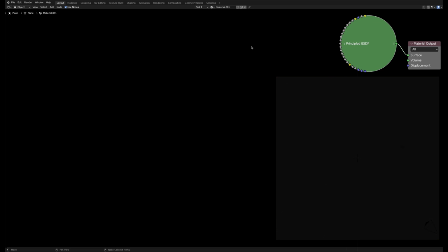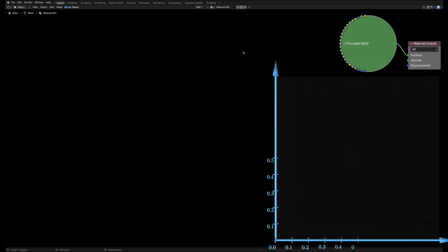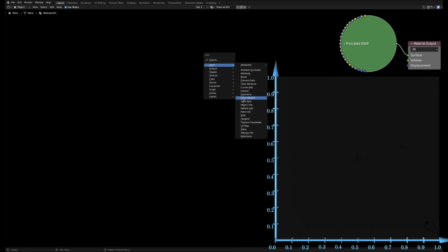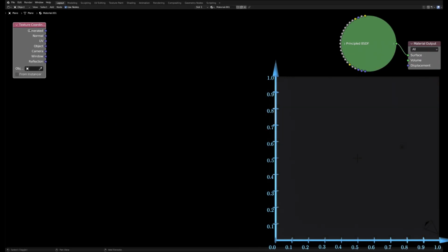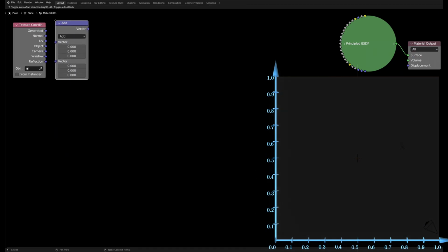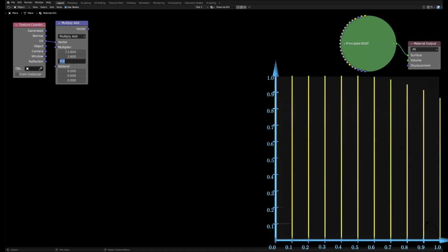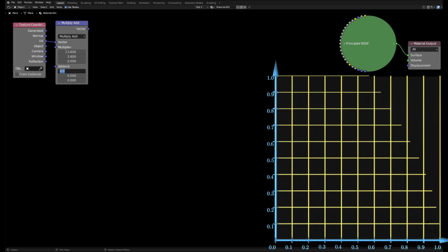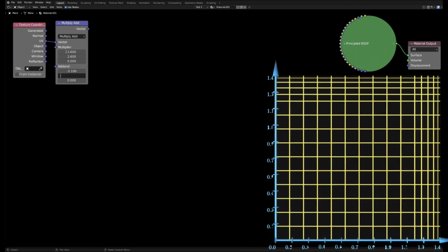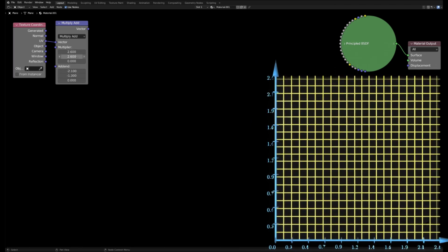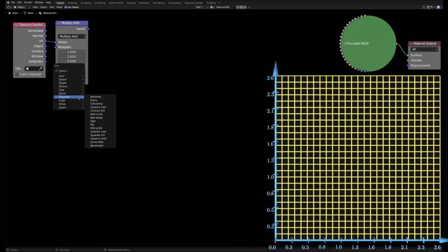The plane is considered to be a two-dimensional coordinate system or a part of the complex plane. In the language of shaders, the plane is equipped with UV coordinates, which range from 0 to 1 in each direction. The first node that we add will rescale these UV coordinates to our demands. We need a 2.6 times larger coordinate system which runs from -2.1 to 0.5 in x direction and from -1.3 to 1.3 in the y direction.